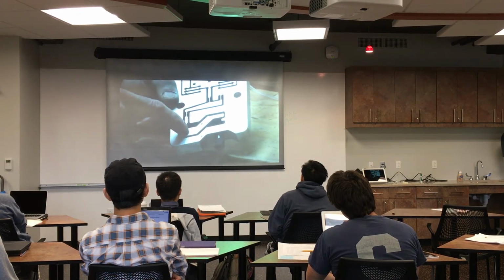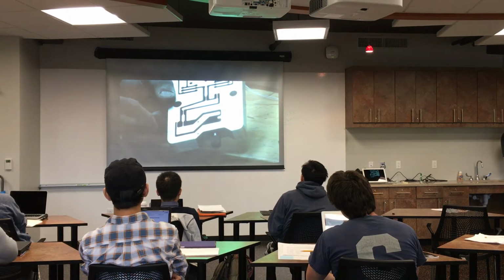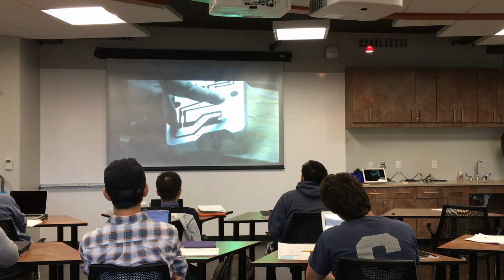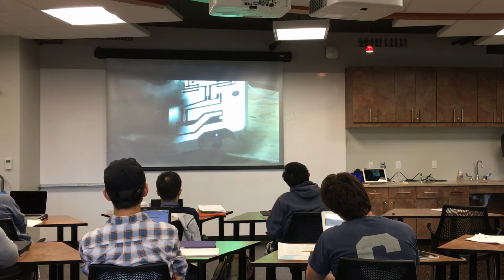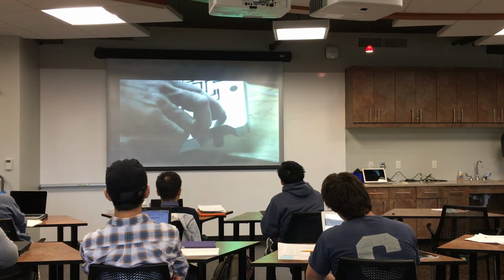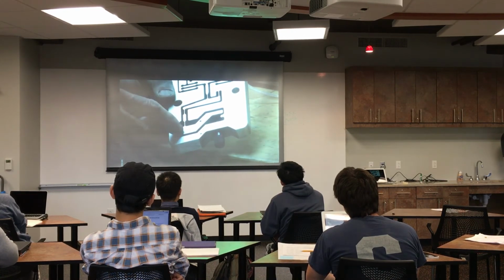This piece is called a wiggle bar. It's used to eliminate the fact that this is actually rotating around the pivot. What you want is a straight line motion, so you have to put in a bar so that the effect of this rotation wouldn't be transferred to the next stage. Basically, it decouples the linear motion from the rotation.